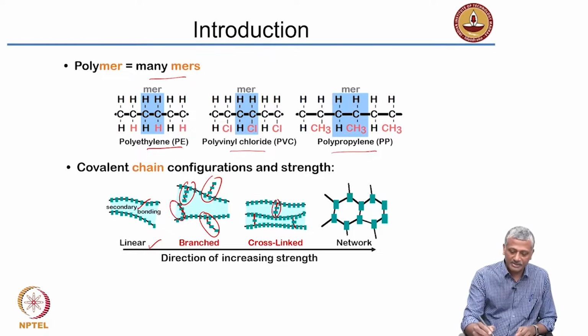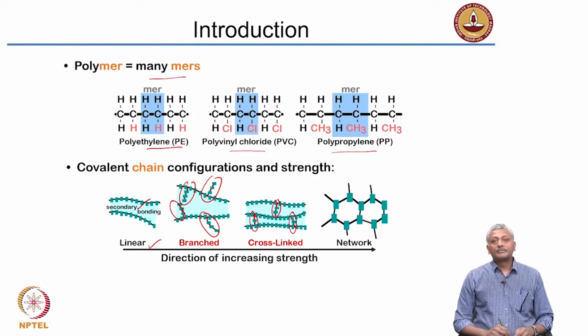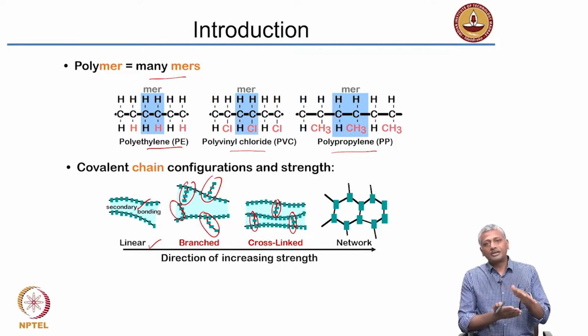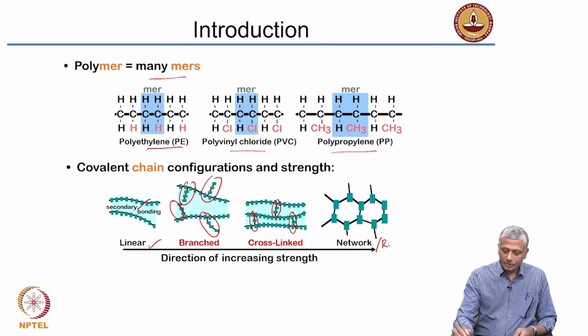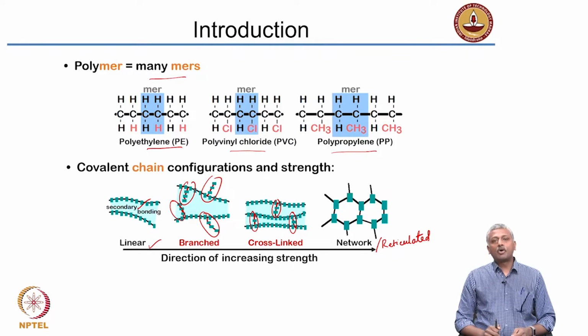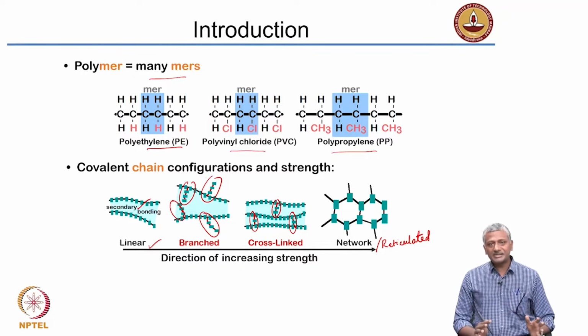So you see here, these links are basically connecting the different polymer chains. Now, obviously, you can realize that this kind of a material will not easily flow, right? This kind of a material, cross-linked material, will be stronger and stiffer as compared to linear or branched polymers. Of course, the highest order in terms of polymers is the network or reticulated structure. Okay, it's also called reticulated structure. So here in the network structure you are forming bonds across the three dimensions. So essentially what this means is you now have a highly ordered network.